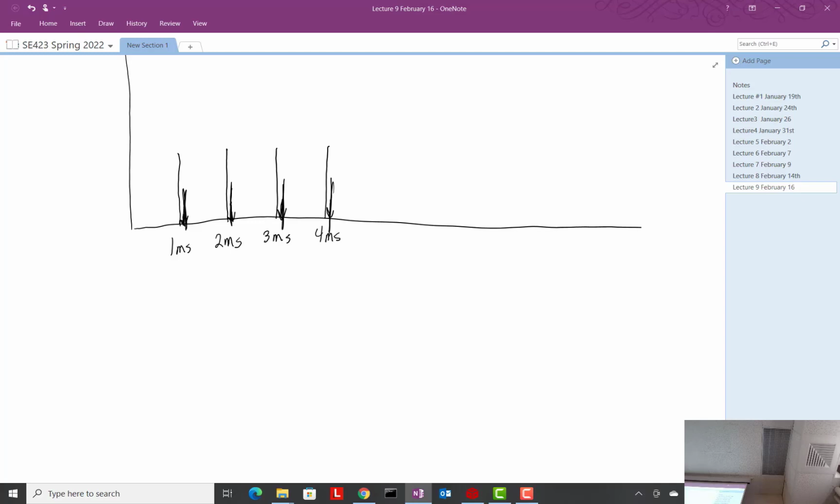Now, if you were doing an insanely fast interrupt, maybe you would, but not when we're sitting here sampling every 1,000 microseconds when the conversion takes 10 microseconds. That's a very small part of that full 1,000 microseconds. Do you get what I'm saying there? So we can just ignore that it took 10 microseconds for the ADC to convert, and just assume, boom, this is where our 1 millisecond is, marching forward. Okay, good. We'll keep on talking about this, but this is not our only lecture on this.